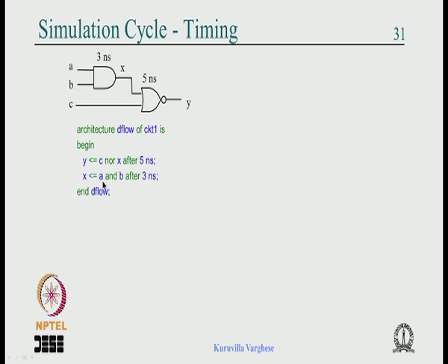Suppose the simulation time is 100 nanosecond, at 100 nanosecond you compute X, and there may be a Z with A, you compute Z, really does not matter, okay. Whatever I am going to show you is a simple case, but that can be extended to a more complex case, only you need to work it out, okay. So the rule of resolving concurrency is very simple. Look at the right hand side of the assignment, wherever there is an event, and compute that, okay.